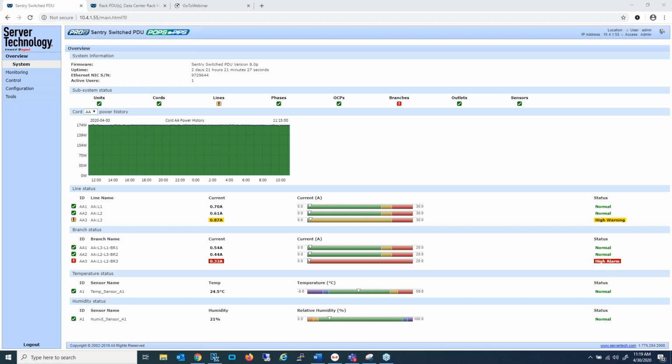So proper, as I attempted to define earlier, would be to plug things in at the top. Now you don't have to go 3 at the top and then 3 in the lower half. You can just load the top, the upper half of the unit, the first 3 branches. You would pay attention to loading those until you get to half of the line capacity. Or actually a quarter in a redundant environment, then you would move on to the lower branch and use only those.